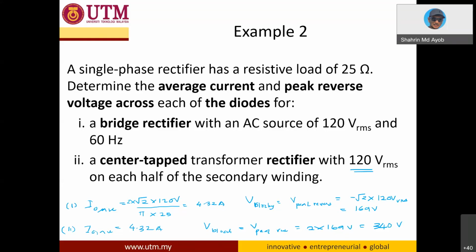If you are more towards the system or product being mobile and very lightweight, don't use center tap, because with the center tap you have a transformer. That transformer is a line frequency transformer, a 50 hertz transformer. So it's very bulky and very heavy. So you need to use full bridge. But the disadvantage of that is you don't have any electrical isolation. Okay, that is the trade-off.